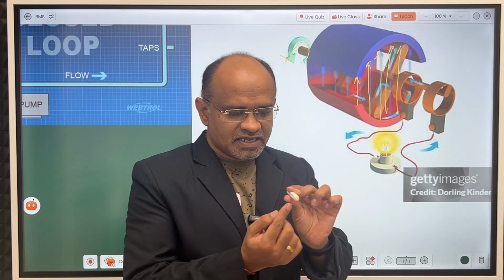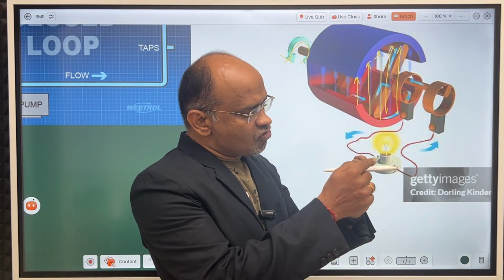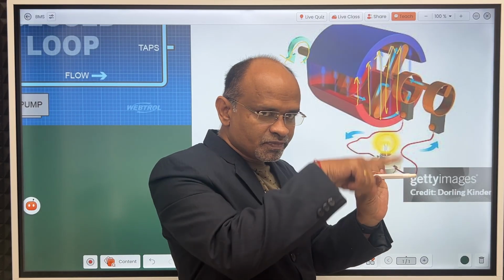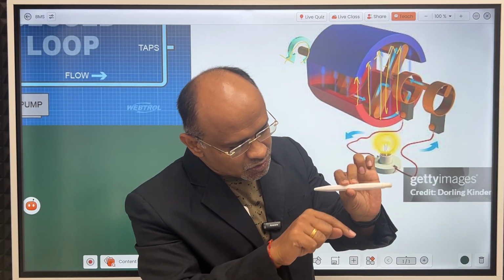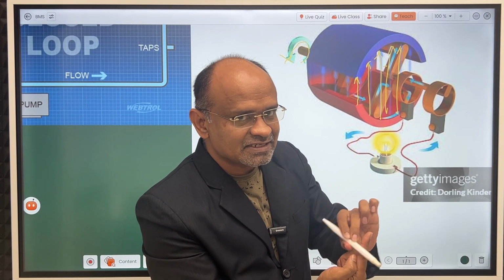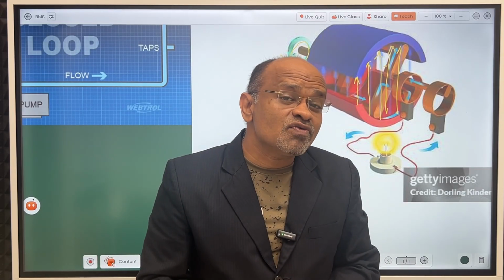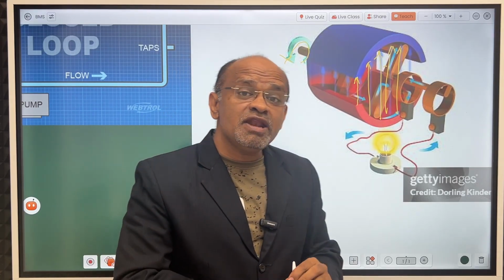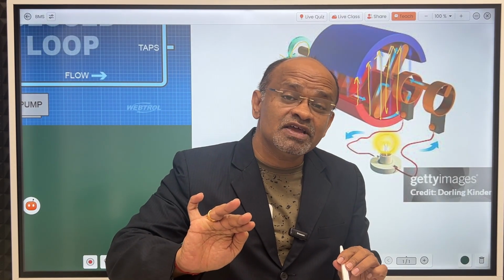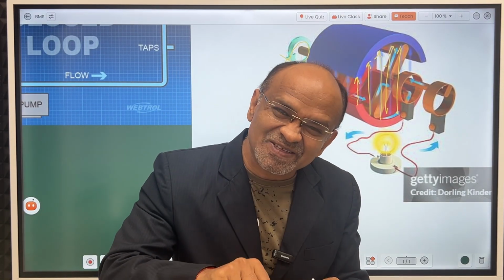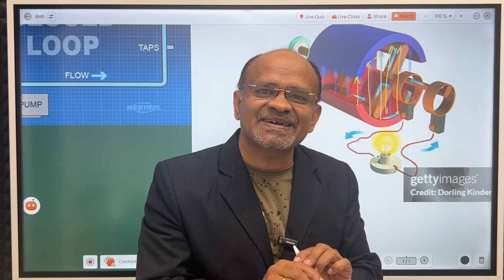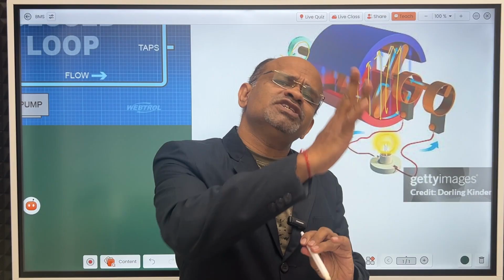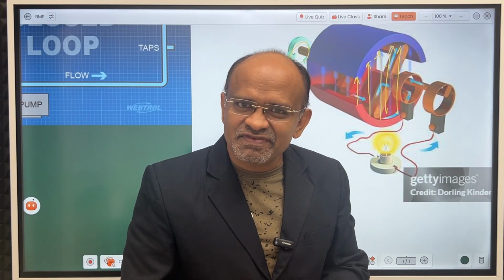In the same way, this is a conductor. These are the magnetic lines flowing from down to up. Now what will happen? This will oppose those magnetic lines. Now in opposition, what will happen? These magnetic lines will push. What will they push? Those free electrons available in that conductor. These free electrons are moving randomly, right? So this magnetic field will push them. And where will they go?